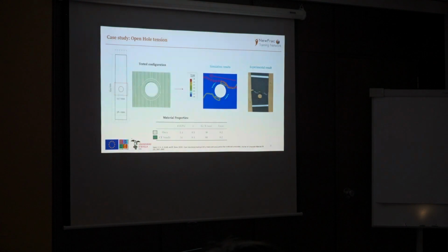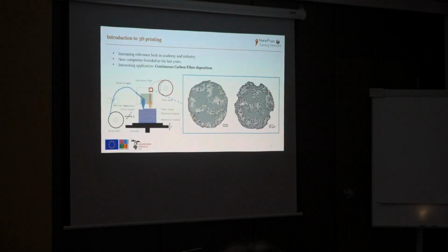That's the problem, because given the material properties, and given also the strength that I didn't plot here in the table, if you just use the formulas for homogeneous materials, it comes out that this length scale is wider than this diameter. So actually, if we consider that length scale value, the approximation of the strength that we have is way better than the one I showed you right now.